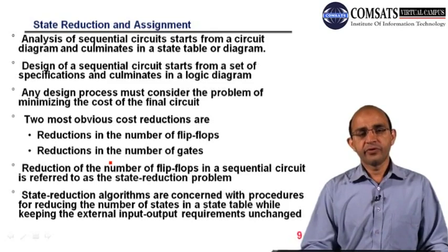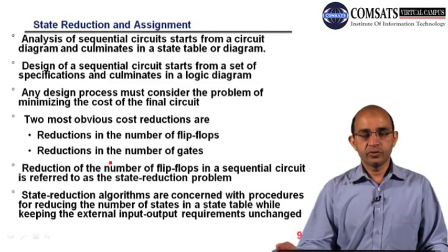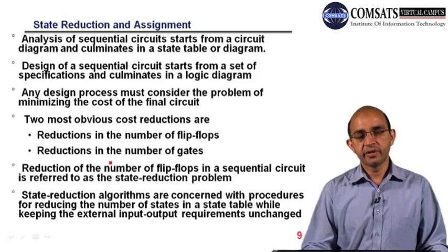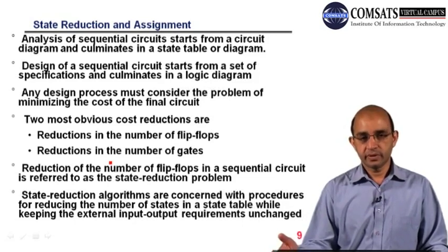But if you have a truth table and you want to simplify, you draw the truth table and go through a certain number of steps in sequence. First you draw the truth table onto the K-map, and then you look for different groupings, pairs, quads, squares, and so on, and after simplification you have the minimum number of gates for the same functionality.